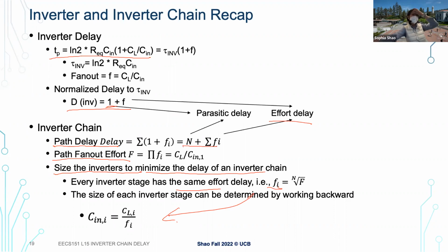So that's how we think about delays. We start from a single MOS transistor, a single gate, then we get to a chain of inverters. Now we see it's not always in our interest to make things as big as possible. We need to consider what's before us and what's after us to optimize the delay. So far our discussion has mostly focused on the inverter. Next week, we'll generalize this to arbitrary gates to see how we can reason about the delay of any circuit. We'll introduce a new concept, what people call logical effort, to describe that. We'll see more next week.